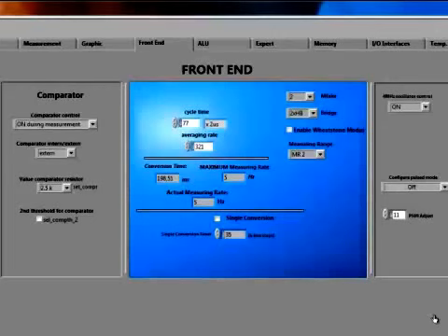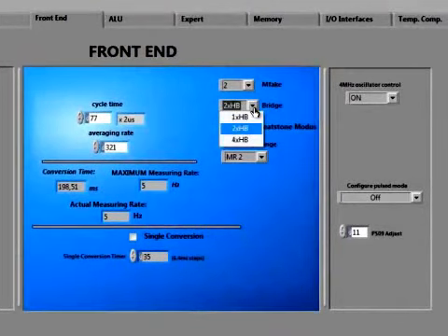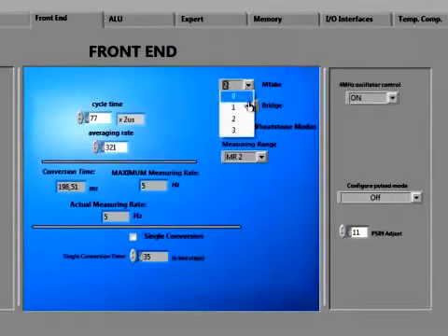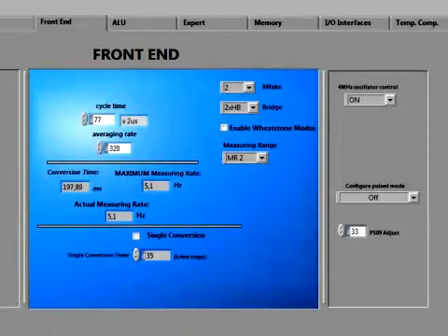Depending on the strain gauge connected to your hardware, you can select the number of half bridges here. The number of fake measurements is configurable from this drop-down box. The enable or disable for the Wheatstone mode is done through this checkbox here. The measuring range of the TDC in the PS09 chip, measuring range 1 or 2, is selectable here. By default, it is measuring range 2.